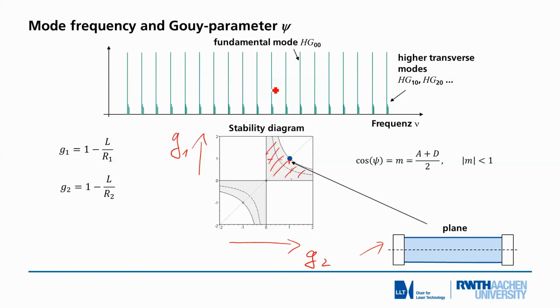So for a certain longitudinal mode, TEM00 transversal mode, this is the frequency. If we have a higher transversal order, 1,1, for instance, then we will have a slight displacement of the frequency, which can be explained by the fact that the resonator is, so to say, a little tilted.